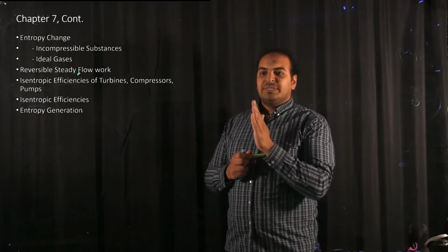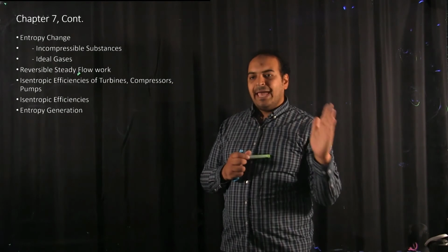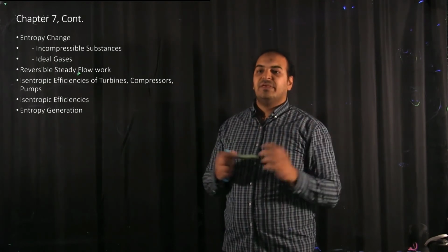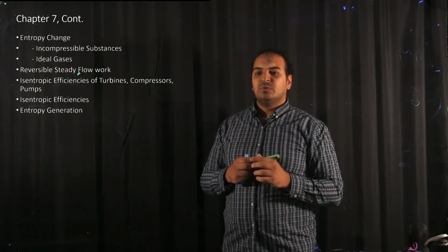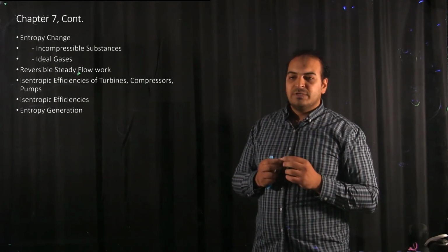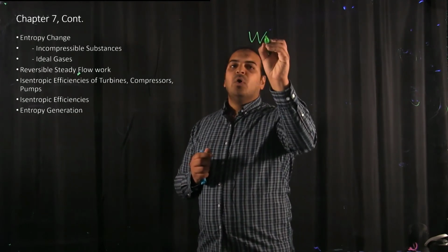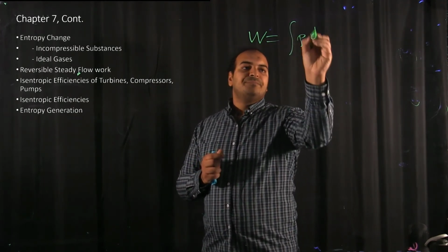So you need to distinguish between steam table, incompressible substance, and ideal gases. These are three different things. And of course, the first one, which is Q over T, applies if the temperature of the surroundings is constant, or an isothermal reservoir.